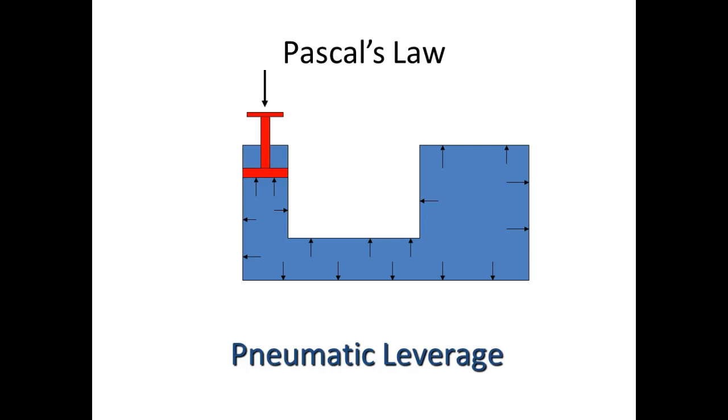So a lot of people don't understand that. They think it's the physical size of the engine, but when we give out those displacements, we're giving the amount of air it can move, or the amount of fluid it can move in what? One revolution, or one stroke. If it was a reciprocating engine, it would be how much it could move in one stroke. If it's multiple cylinders, it's how much you can move in one revolution.